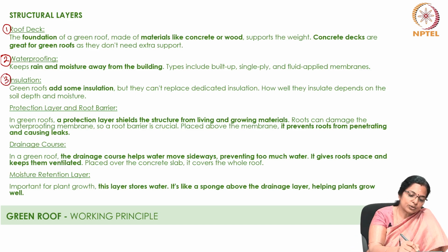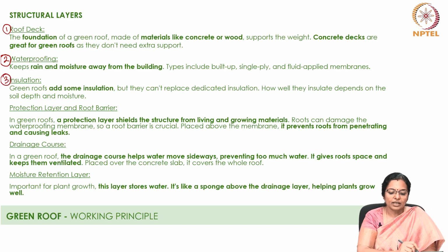Third is insulation. Green roofs require some insulation, but they cannot replace it. Green roofs themselves add some insulation, but that cannot replace a dedicated insulation. How well they insulate depends on the soil depth as well as moisture.